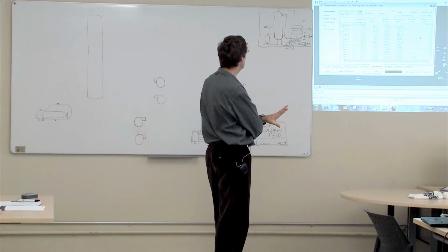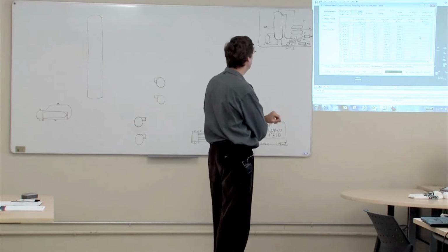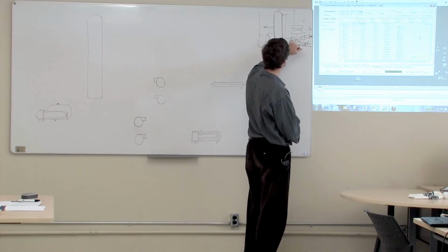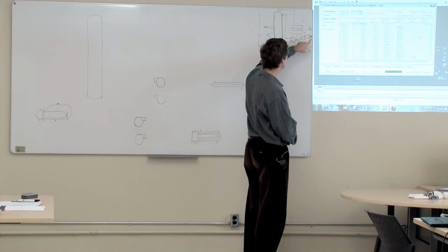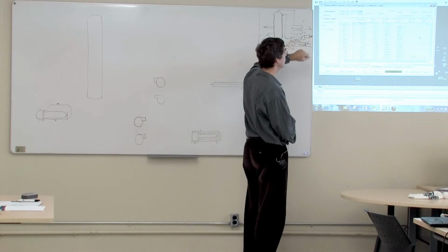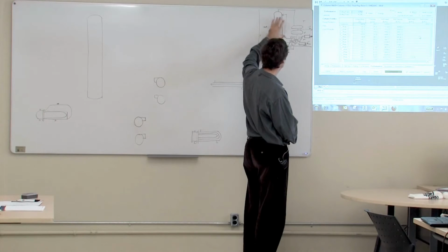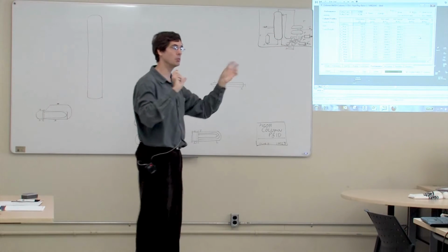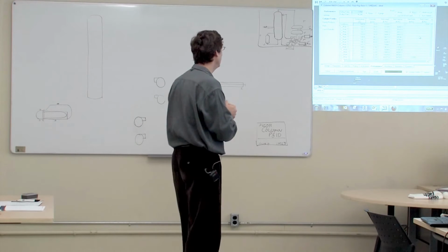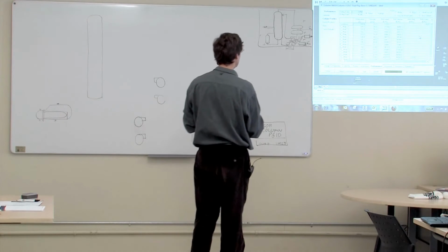I haven't done the hydraulics calculations, but this is a fairly tall tower, so this probably will have the greater differential pressure than this one that's going to go out to the storage tank. But I don't think it's going to be that different. I'm not going to two processes where one process is dramatically different in terms of pressure that I have to get it to.